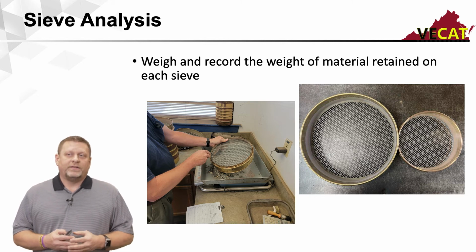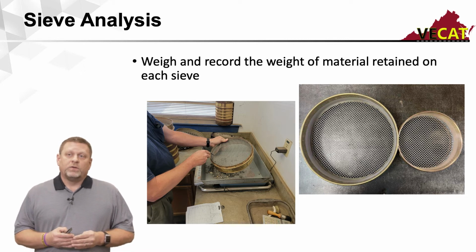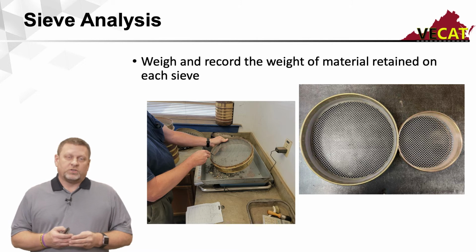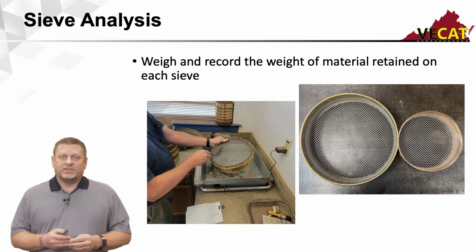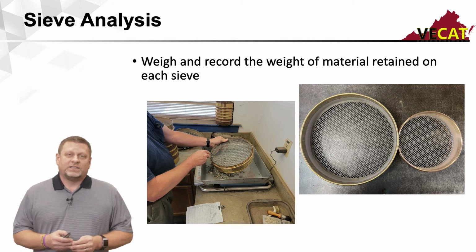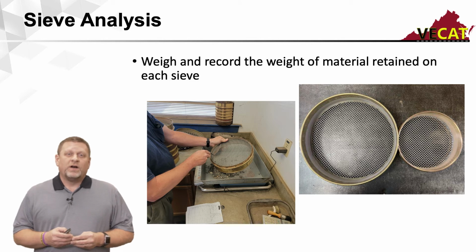Wanted to point out that typically used to be, before SuperPave, we used Marshall specimens. We worked with smaller samples. These smaller samples then were regularly tested on 8-inch sieves, and I still see a lot of 8-inch sieves used throughout the industry. Those are now classified as a soils sieve, and the larger diameter 12-inch sieves are classified as aggregate sieves. And you'll see more throughout this presentation of the importance of having a large enough sieve to do proper representation.